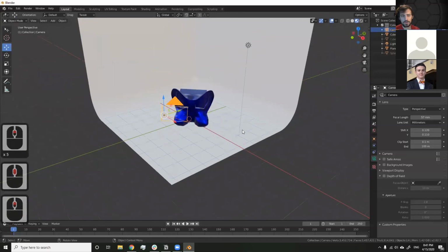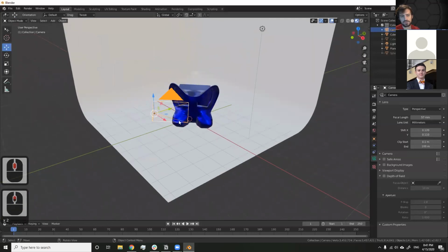So basically anything that's super, super close to the camera, 0.1 away from the camera, it won't render that. Anything that's really far away from the camera, it won't render that either. By default, these are pretty low values, but you can always increase your clipping way. So you can turn this way up so things in the distance will be captured into your render.